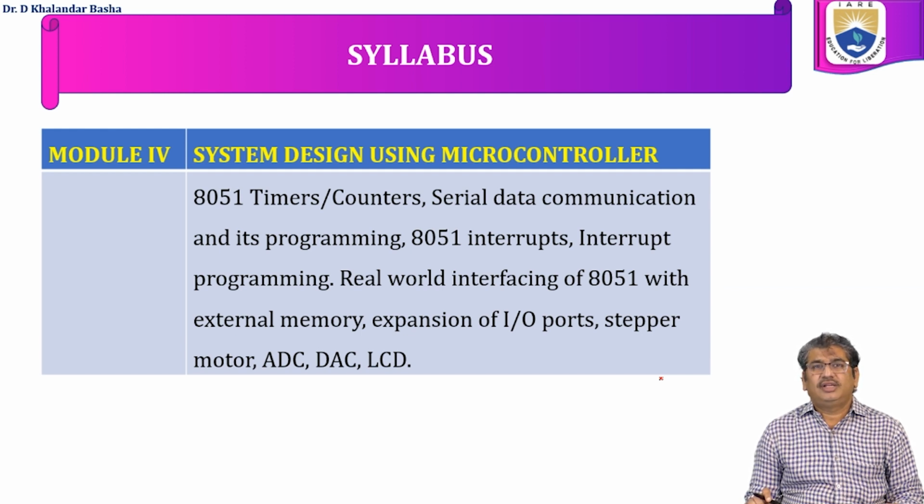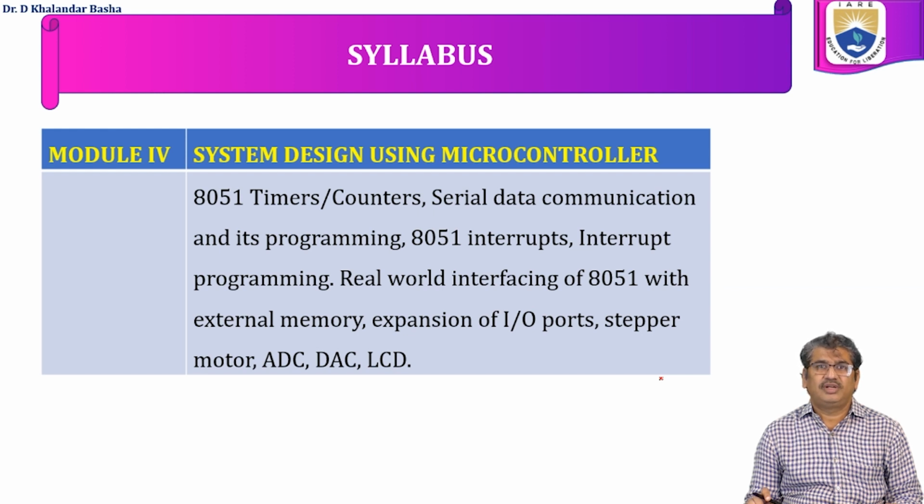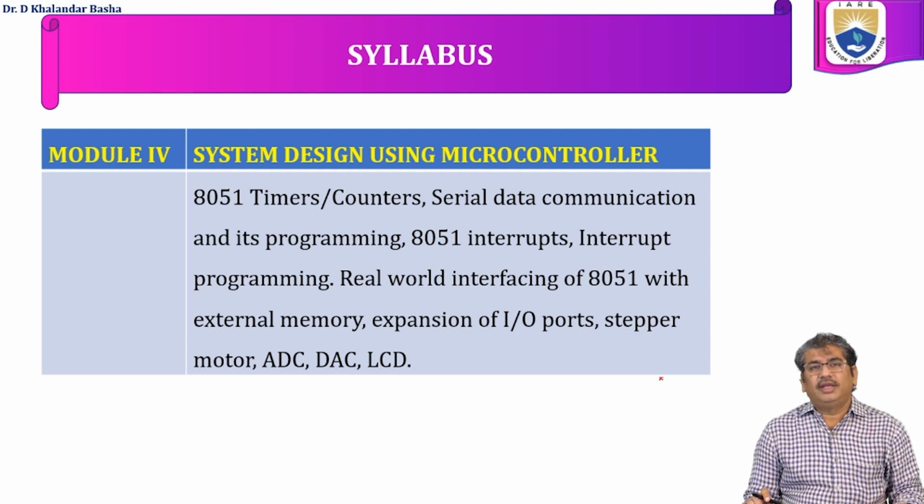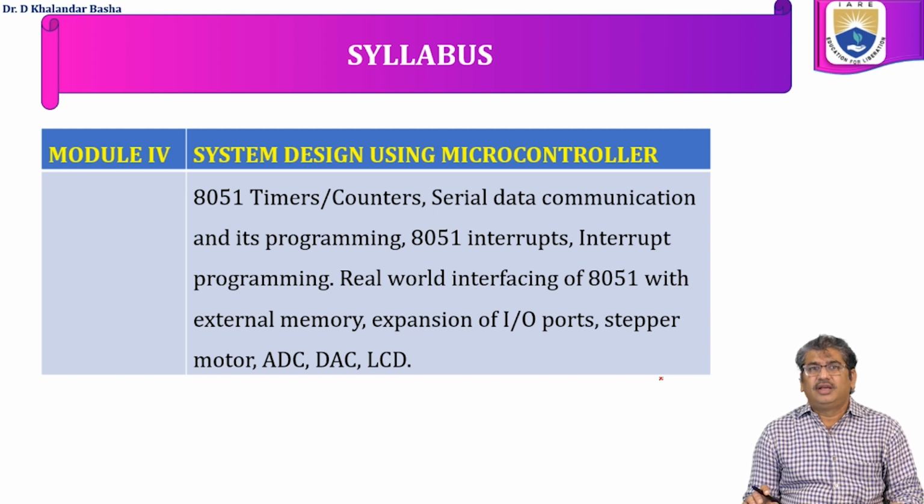Serial data communication is for transmitting or receiving data. The 8051 supports UART, that is, the universal asynchronous receiver transmitter. We can see how the data will be transmitted or received in serial data communication. The various SFRs corresponding to serial data communication are SCON and PCON. Here also the data will be transmitted in 8-bit size and 9-bit size. How to configure these SCON and PCON registers, we are going to study in detail.